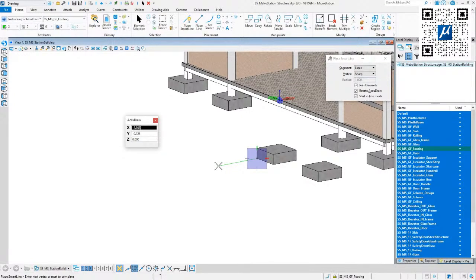Let's say the next element that I want to draw is located in the top view of my drawing, in the XY plane. And the top view you can get with the T shortcut. So I press T, and AccuDraw is moving to a top view. You can see this rotating. And there are two other keys available.